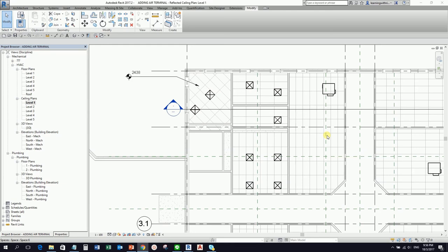And the connections of our air terminals to our duct will get lost. So that's the problem if your air terminal is ceiling hosted and suddenly you move the ceiling: all the connections will break. That's why most of the time our air terminals are non-hosted. I just prefer them floating instead of breaking the connections from the duct.